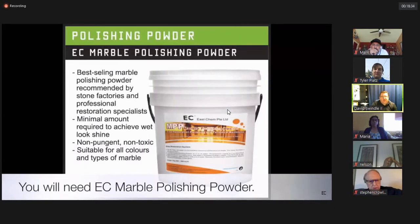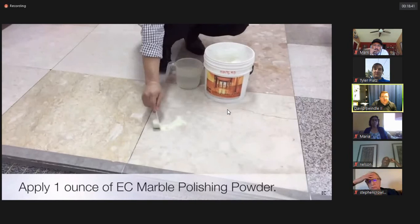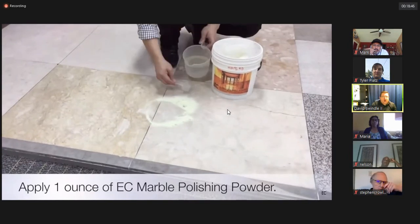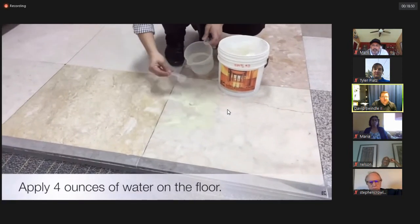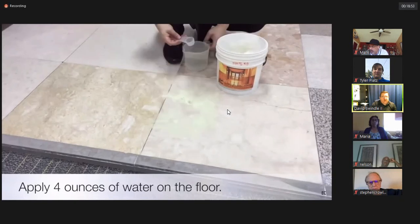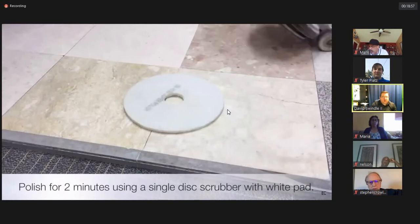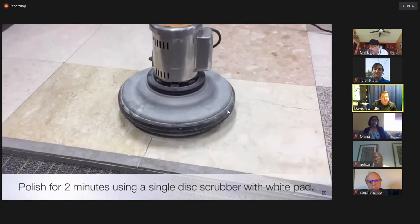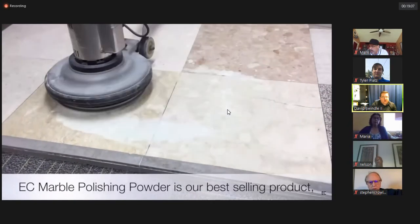A lot of different companies have different marble polishing powders that do this. They don't need much, but the powder is applied directly on the floor, and they don't want a lot of water. They're simply creating a little bit of a paste. In this case, it was a ratio, a certain amount of water to a certain amount of powder. Notice how it creates that paste, a little bit of a slurry paste.